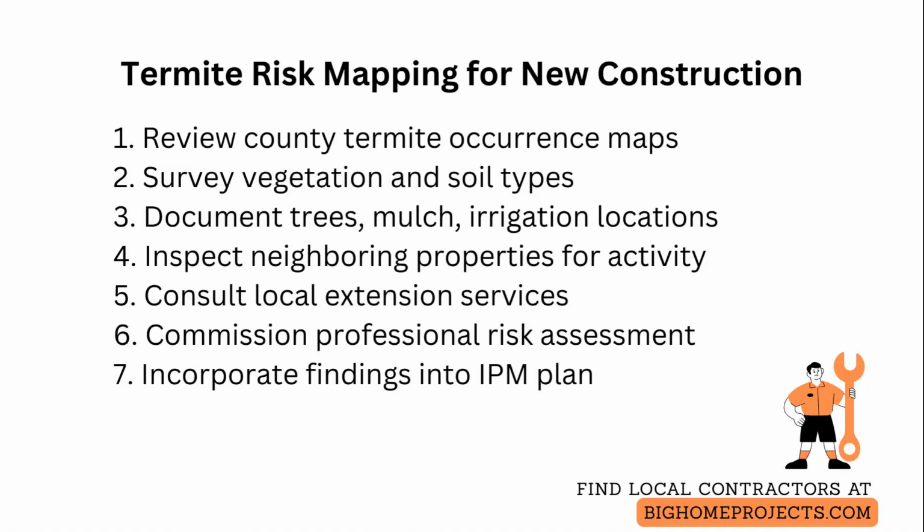Inspect neighboring properties for visible mud tubes, damaged wood, or untreated structures since termites can travel across yards. And recent activity next door greatly raises risk on the lot. Photograph and log distances to any active signs.